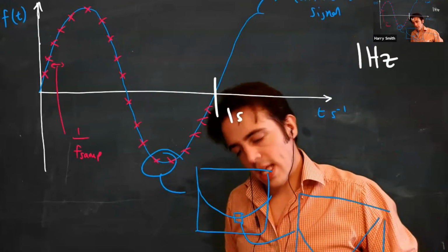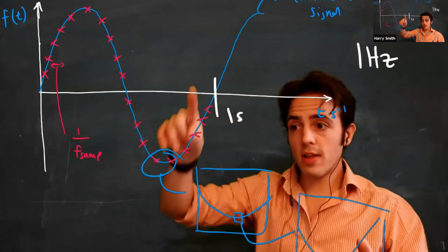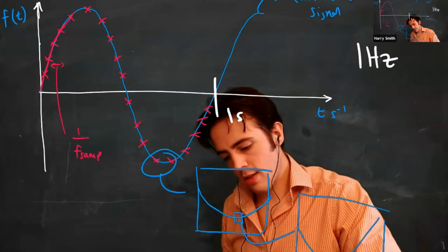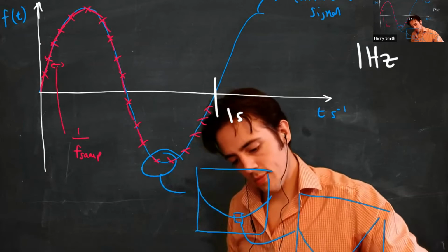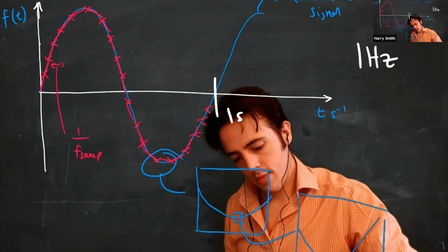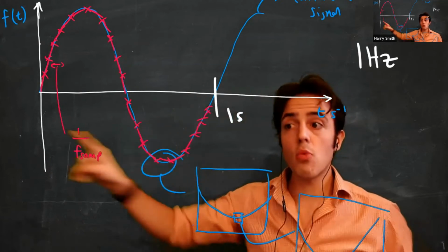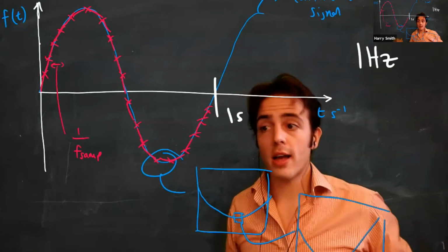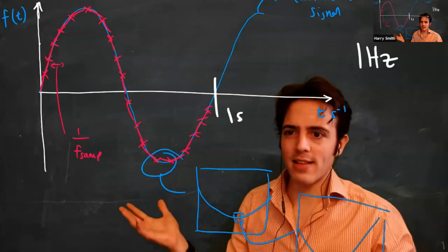So let's have a think about this. If I want to reproduce this signal, then if I were to join up each of these with a straight line, I'd get a pretty good reproduction of the blue signal with that many samples being taken. I could take loads more samples, but I just have a bunch of redundant data there.